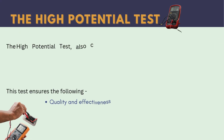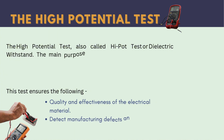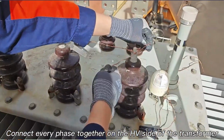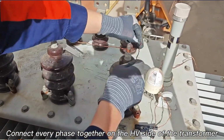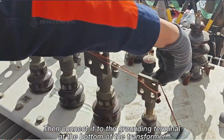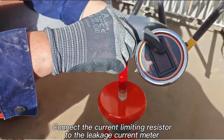Next, the high potential test. The high potential test, also called high pot test or dielectric withstand test. The main purpose of this test is to determine the quality of material used in insulation and components so that the equipment can withstand the suitable high voltage without any failure.